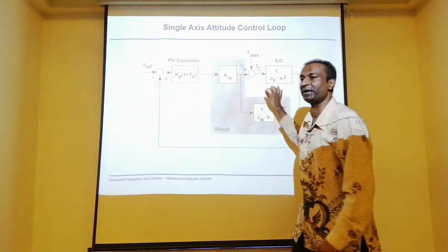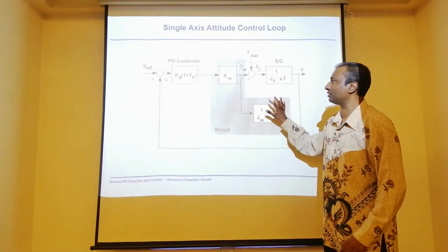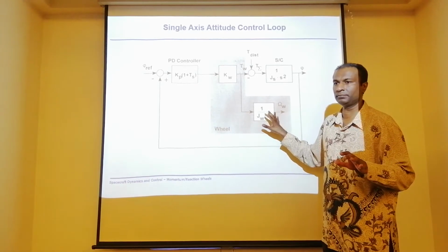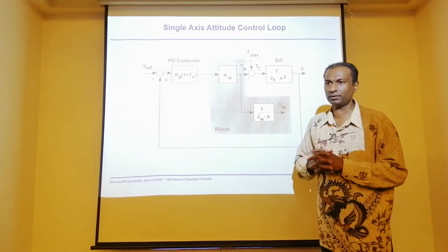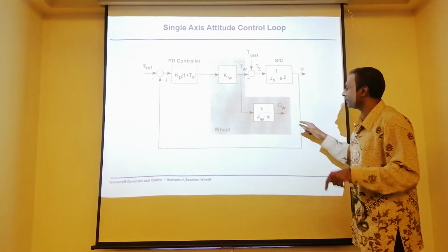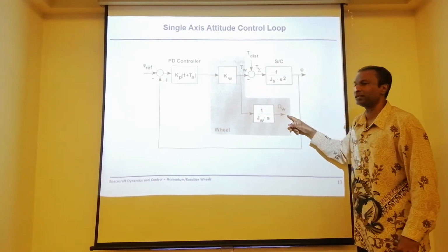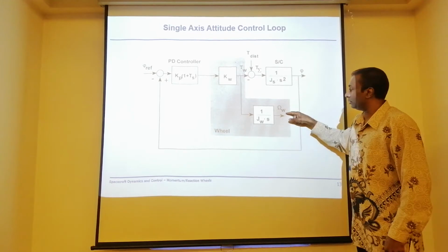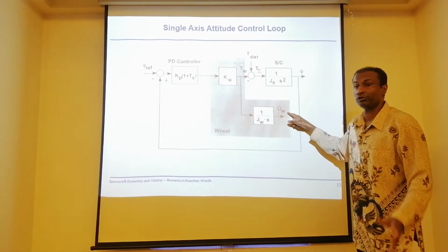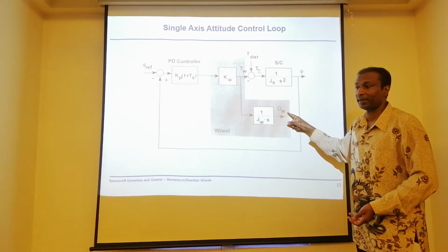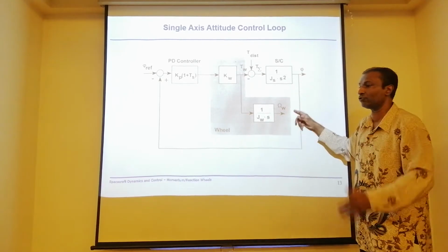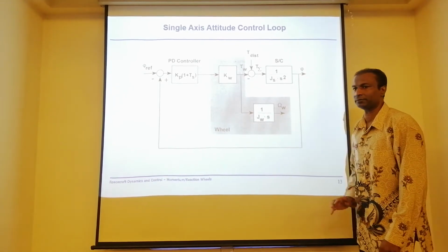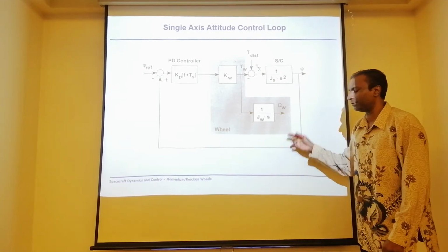So this is the typical scheme of an attitude control system for a satellite with a reaction wheel. Very easy, straightforward. This gives you the actual wheel speed here. So the maximum wheel speed here is going to be what? Let's say I have 5000 RPM, maybe it goes up to about 4800 RPM. I cannot go higher, so I need to do something. Okay? Now remember this.